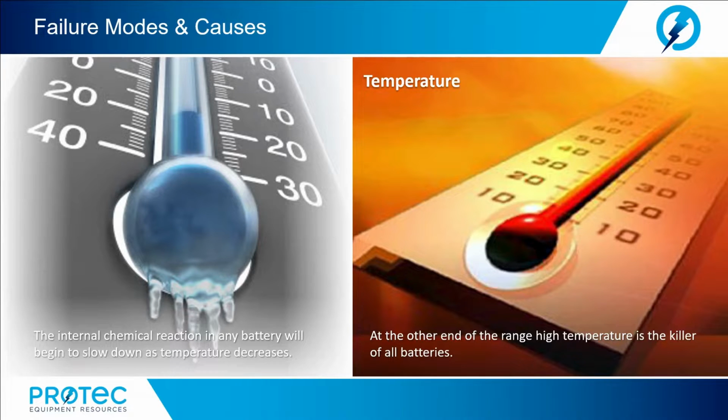Now, a battery is rarely held at a temperature for its entire life. A more realistic scenario is for a battery to heat during the day and cool down during the night, with higher average temperatures in the summer and lower average temperatures in the winter. Unfortunately, cooling the battery off to 77 degrees Fahrenheit will not gain back the life that was lost at the elevated temperature. Once the positive grid corrosion begins, it cannot convert back again. Furthermore, positive grid corrosion occurs at all temperatures. It is merely the speed of the corrosion rate. The result is to control as best as possible the temperature of the batteries in the network.